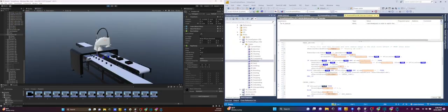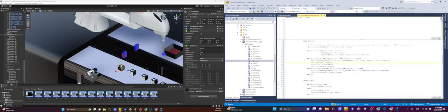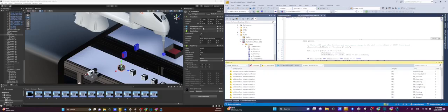So here I can see that the states are going through get ready, index conveyor 1, and read QR code. So it's just flying through this state here and looping back to get ready, and for that reason it's rejecting every product. So which tells me that the vision is not resetting, and it's because I forgot to add these lines. So if we add this,